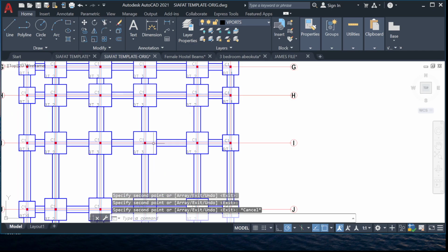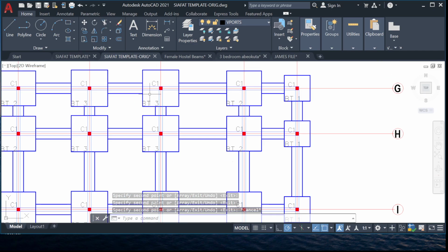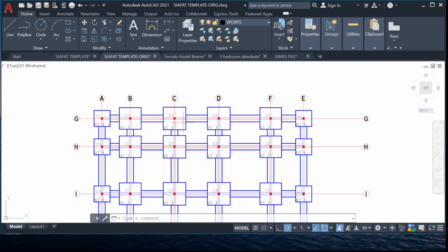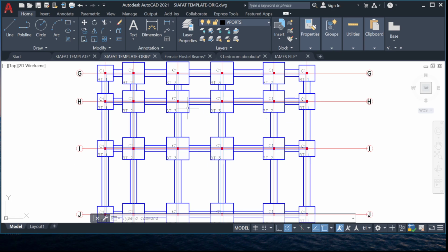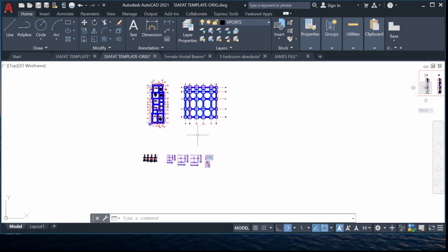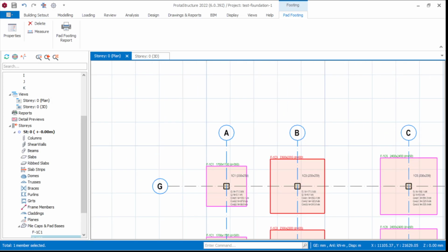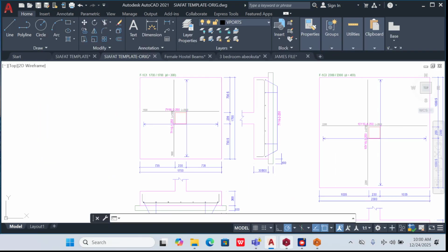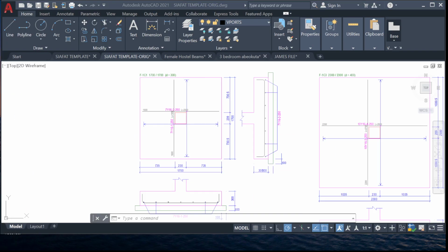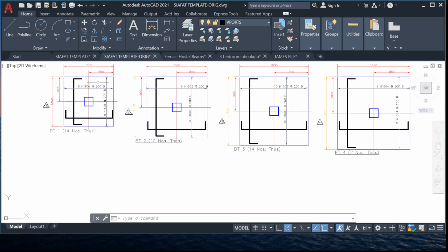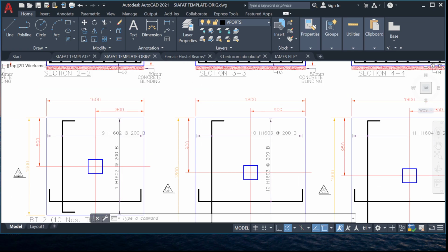Very good. So you see that the structure is coming out very, very nice now. Okay, so we have all the namings in place. The next thing we need to do now is to look at the reinforcement detail of the pad footing. The first one is 17 by 17, which is BT1. So let's take it to this. And what do we do? Let me see the one I can pick. Okay, I have a 16, I have a 18.